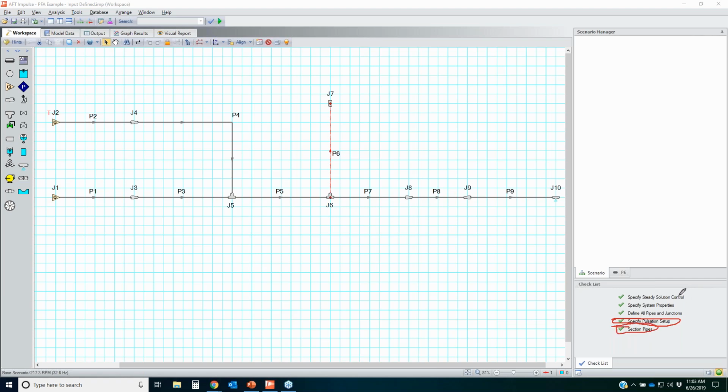And then once that's all done, you just go through, run the analysis, and go back to your base scenario where you have determined what your natural frequencies are. That's my base scenario. And then based upon those natural frequencies, evaluate the pump speeds that can cause those frequencies to happen, and evaluate your pulsation response. It's as easy as that.